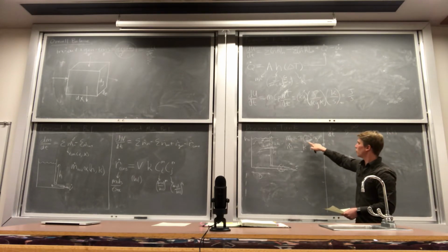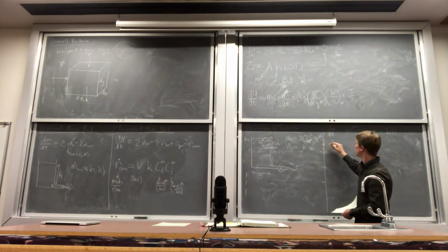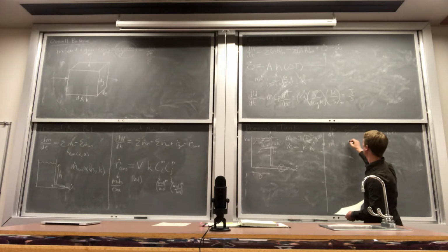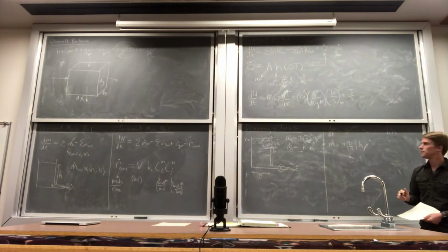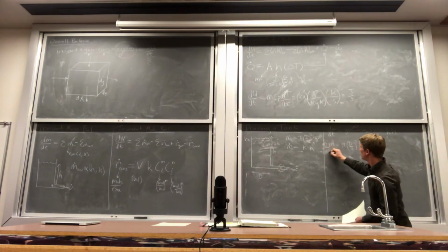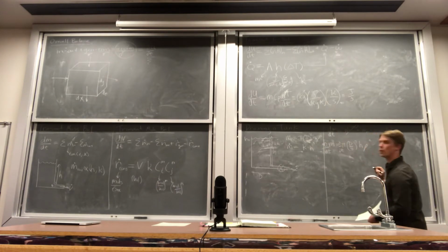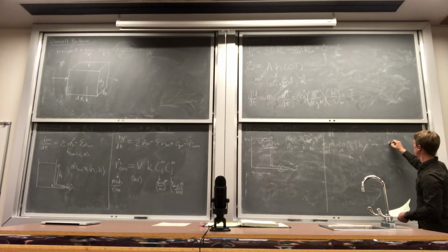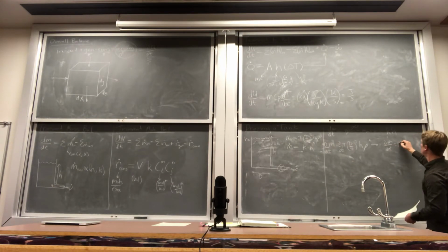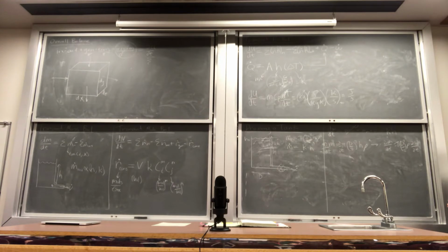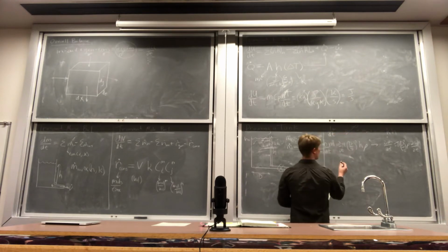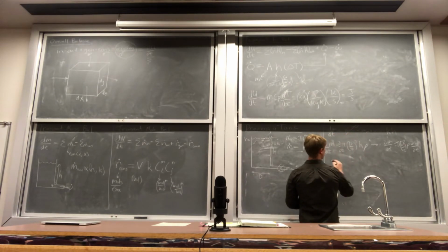So we're going to take this formula here for our initial mass, and we're basically going to differentiate it. So m is equal to pi d over 2 squared h times rho. I'm going to take the derivative with respect to time of both sides of the equation, and I get dm dt is equal to pi d over 2 squared times rho dh dt. Substitute it into my material balance, and I'll do a little bit of rearranging.